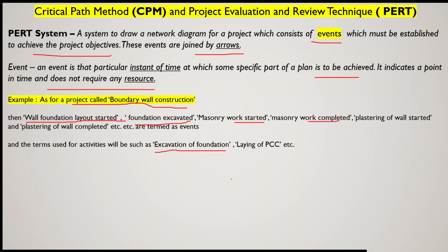Start of excavation of foundation or completion of excavation of foundation will be an event. So events are connected by activities, or you can say activities are connected by events. Similarly, laying of PCC is one type of activity. So if there is any foundation work, then we first have to enlist the various activities, then all those activities will be connected with the help of events with each other.